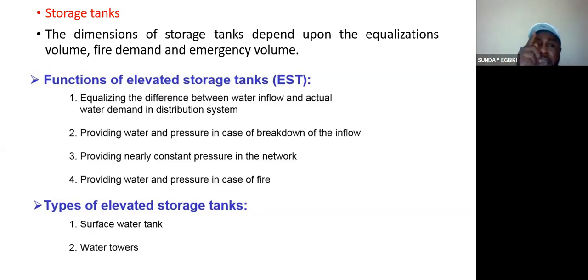Remember today, I said to get the water demand in your estate, you get the total population and multiply it by about 130 to 150 liters per capita per day for one person. You will get the total water demand. The question is, is that total water demand what you are going to use to size your overhead tank? If it is 50 cubic meters, are you just going to design your tank to meet that? No. If you do that, you are over-designing your tank.